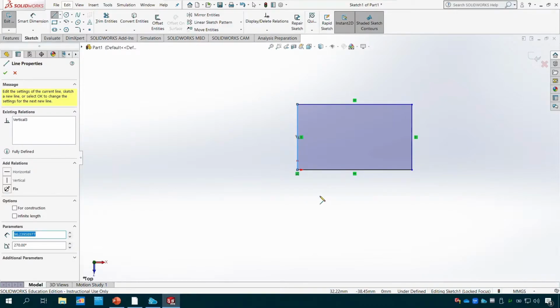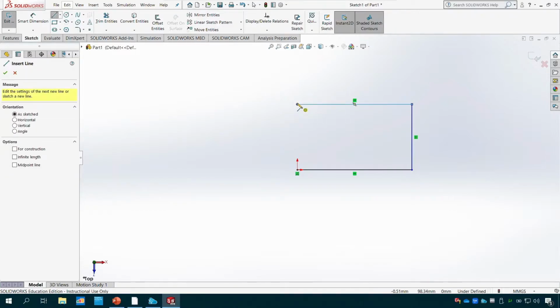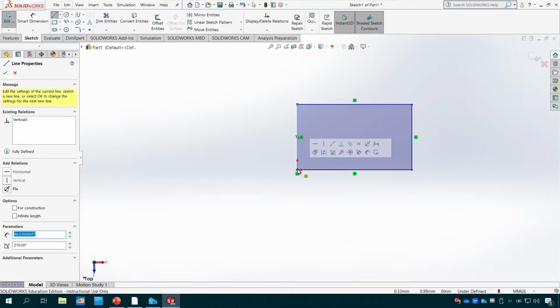One of the question now you might ask, you see now once I close the line here become blue. The reason for it is one of the ways that Solidworks is trying to visualize it for you, that you have a closed curve. You basically close the model. The reason it's really important for you, you realize once we go to the 3D modeling, you need to have a closed curve, basically closed line or closed curve, in order to be able to convert to 3D model, and that's why the software is trying to highlight it for you. So let me do Control Z. You can see right now, because it's not closed, you don't see any kind of visual blue light there. But if in case I close this one down, you can see now it become blue.